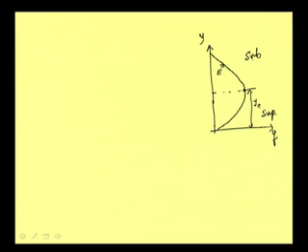But if the flow is in the subcritical zone, then with the increase of unit discharge, depth is decreasing. When Q is increasing in this direction, depth is decreasing. And if you are in the supercritical region, then with the increase of unit discharge, your depth is increasing.